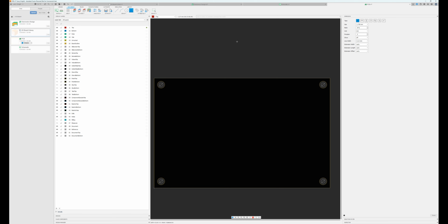And so dimension's a little bit tricky. You click on the hole and it goes from the center, but it does the diameter by default. So you just right click, and then that puts it into the regular mode, and you click, and then you move up like that, and then you got your dimension. So it's 88.9, and that's exactly what we want.